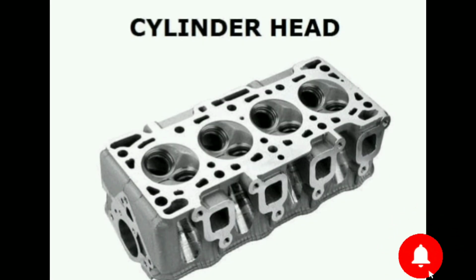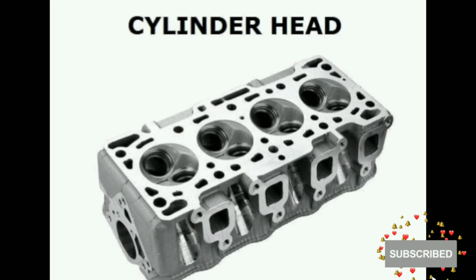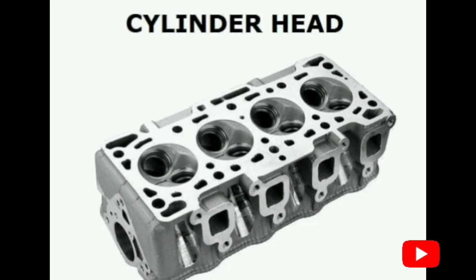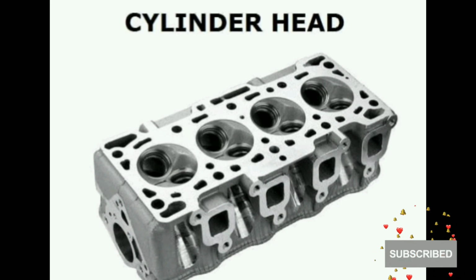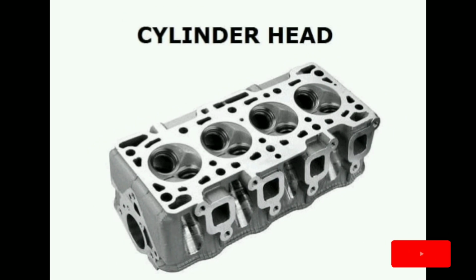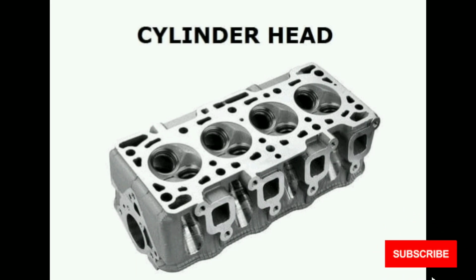This is a cylinder head. The cylinder head is located between the cylinder head cover and the cylinder block. That is what you have to keep in mind. Its purpose is to provide the mounting place of the valves. This is where the valves of an engine are located, and this is where the coolant jacket or an oil gallery for lubricating engine components or cooling is also located.